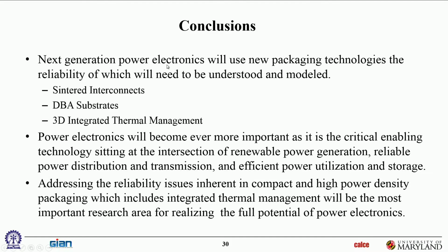So basically, in power electronics, we're looking at new materials, sintered materials, TLPS materials, and new architectures, moving away from wire bonds and everything to planar packs. And the IGBT technology is also evolving. They're going up to higher and higher speeds, higher frequencies, and higher current densities and wattages. So they're making some pretty innovative changes to the IGBT technologies at the silicon level.